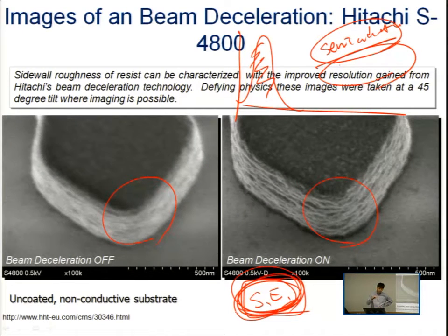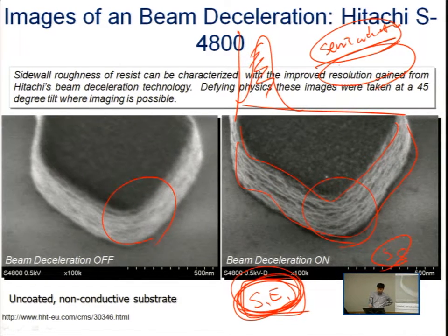They build up on the skin of your insulator samples and locally build up an electric field. Then when the next primary electrons come down, that locally built electric field deflects the beam, and you cannot make the right shapes. Instead of a steady-state image, because of the deflection of the electron beam, your image seems to keep flowing in one direction.